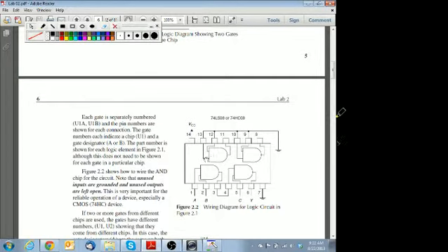Now that's because, first off, if you connect the output to ground, that's going to create a short circuit because the output is a low impedance. That means it's like a power supply. Anytime I say the word low impedance, that's a property of a power supply or a battery or a source. And if you connect this to ground, then that low impedance 5 volts is going to be going to ground, and you can use Ohm's law to figure out 5 over very low is going to be equal to a lot of current.